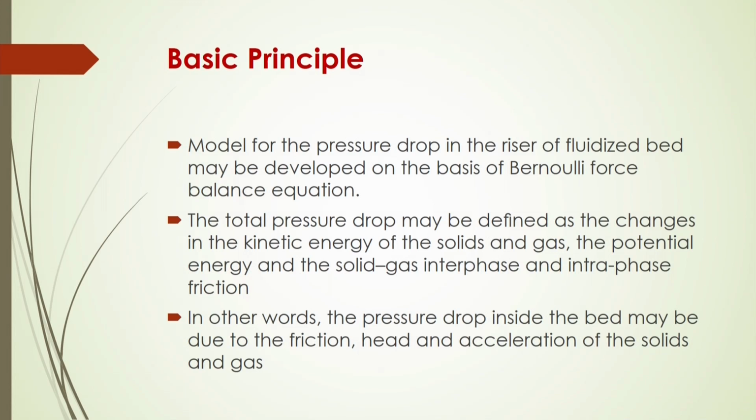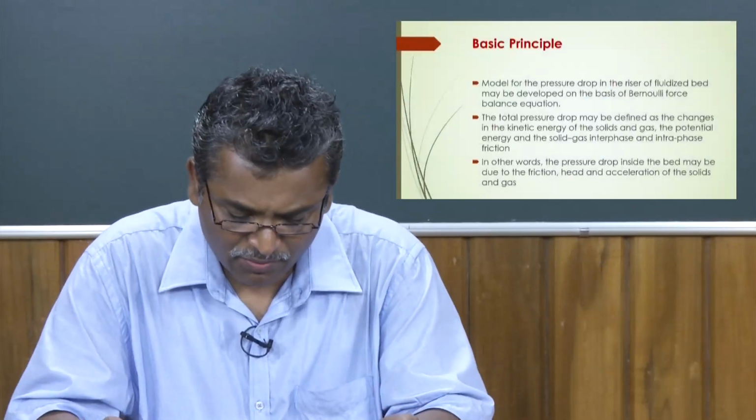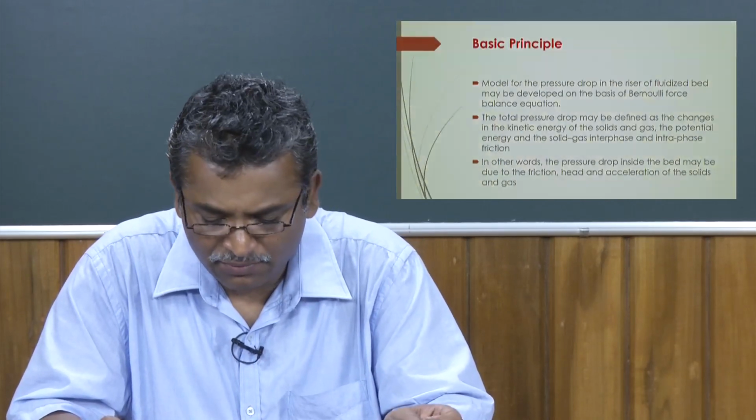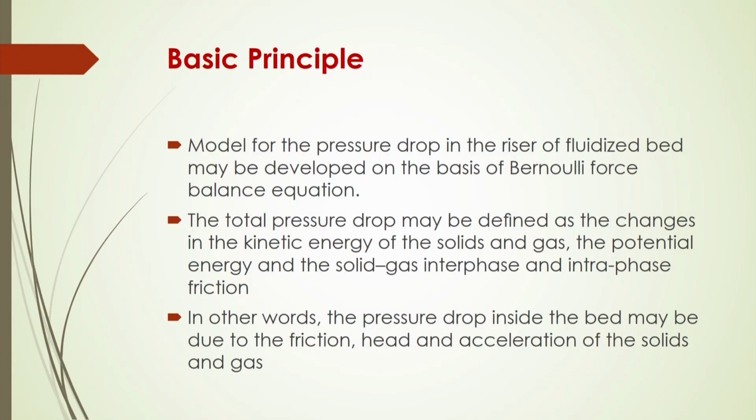Another important point is that we should know the basic principle for pressure drop analysis. There are several models to analyze the pressure drop inside the bed. The basic principle is that a model for the pressure drop in the riser of a fluidized bed may be developed on the basis of Bernoulli's force balance equation. As per Bernoulli's equation, the total energy will be constant.